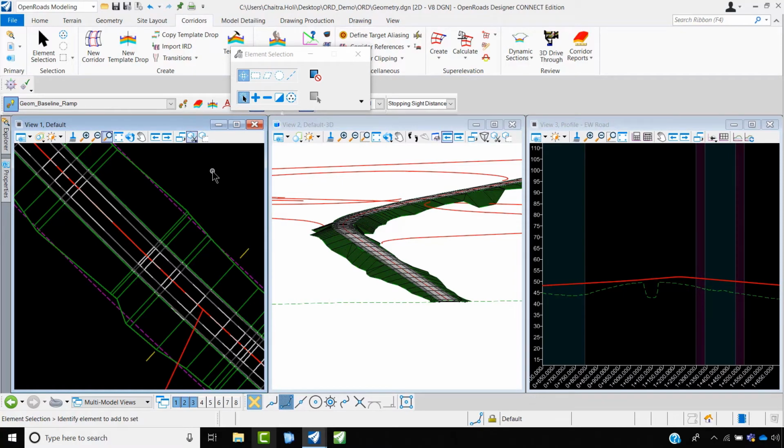So now you would want to know where exactly these templates are present and how I could review those templates. For that, under this Corridor tab, under the Create category, you have a Template box where you choose Create Template.